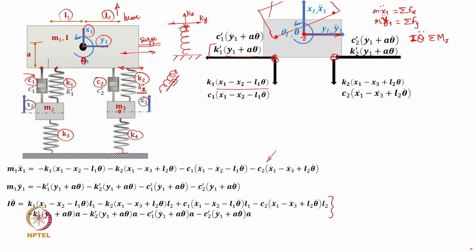If we assume this free body to be moving in the positive direction of all the degrees of freedom, then when it moves from its original mean equilibrium position, the displacements in the connection springs as well as dashpots are something you can find out yourself, and that will give you the restoring forces at both connection points from the two suspensions, as well as the dissipating forces generated in the dashpots of the suspension.